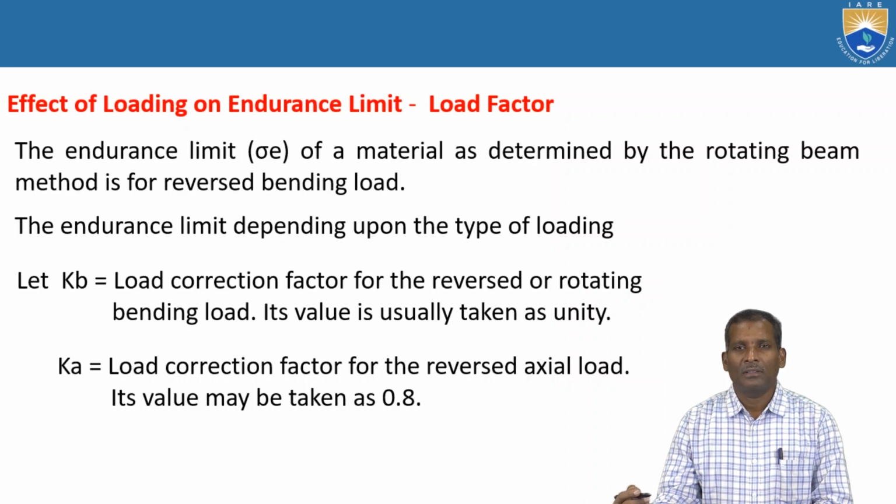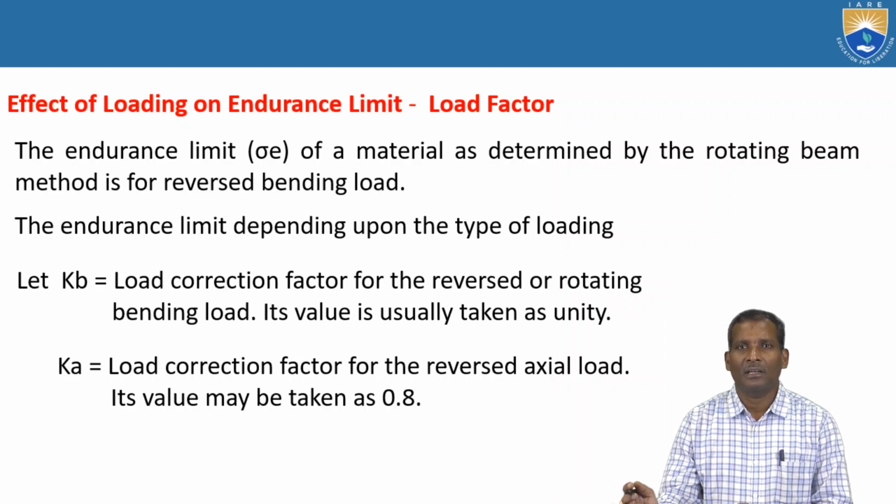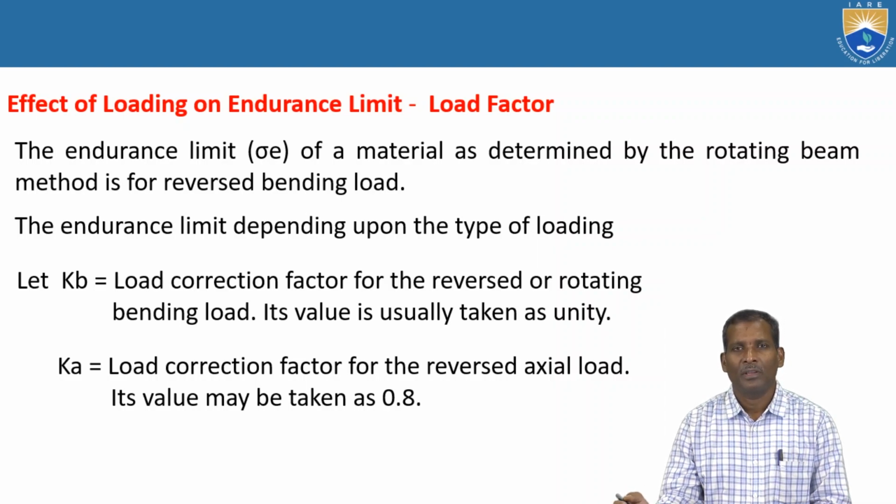Sometimes the mechanical members are also subjected to loads other than reversal bending loads. It may be subjected to axial loads. It may be subjected to shear loads. In that case, you have to calculate the endurance limit by taking the load correction factor for the corresponding loads.